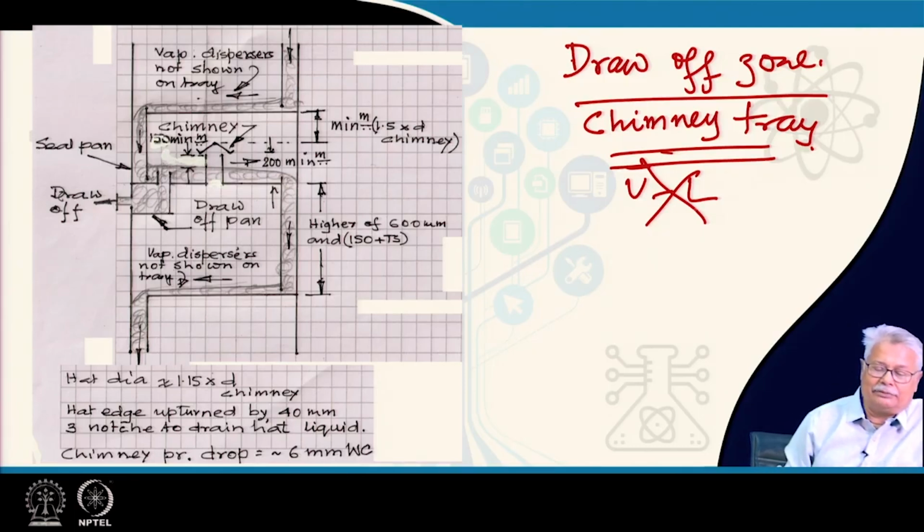We have a scheme of an arrangement which is there in case of the draw-off zone. What you have here is a tray. The tray goes like this. This is the tray deck, and here is its downcomer. The upper tray fits this particular tray through its own downcomer. So, naturally, this is the direction of the liquid coming in, falling down and going out. Now, it flows across this and comes down. We do not want any vapor and the liquid contacting.